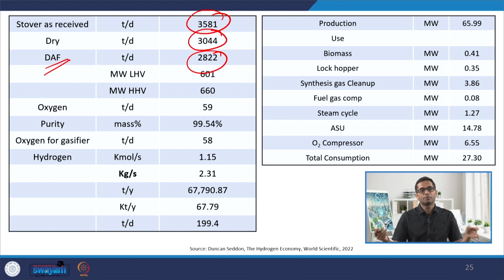air gasification, because air gasification, as we have understood in the last class, would mean that there is going to be a significant amount of nitrogen in the gas, and then that needs to be cleansed downstream. So better than removing 50% of the gas composition as nitrogen, it is always advisable why would you let nitrogen enter the system altogether, and that is why we are aiming at oxygen that is getting utilized directly.